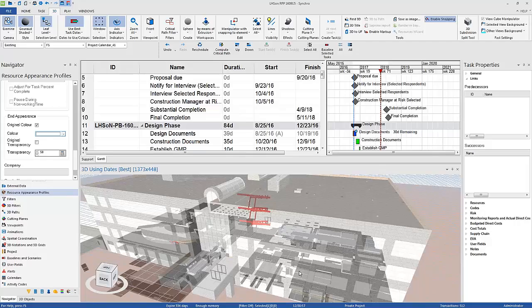Because they both needed to install steel below in this area, we did a 4D schedule of just the shoring. When I say shoring, it's scaffolding. It's structural scaffolding that's going to be like 4 stories tall. But when you're building 4 stories tall scaffolding, it's very heavy, so below it has to have steel to support the weight. The problem is we were also installing other structural steel at the same time, and we needed this scaffolding installed because we're installing these lights that were 70 feet up in the air, and the only way to build them is to build the structural scaffolding.